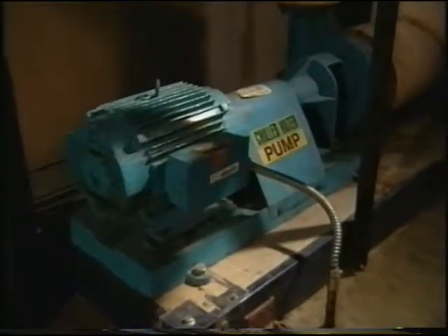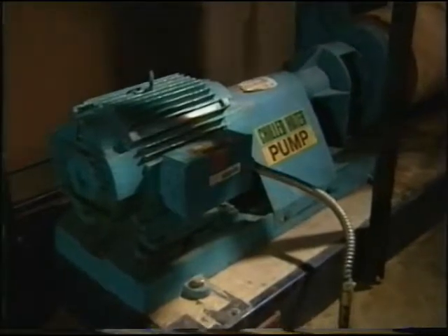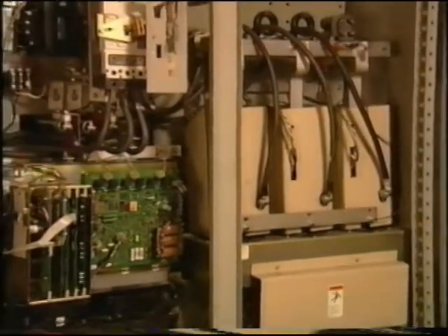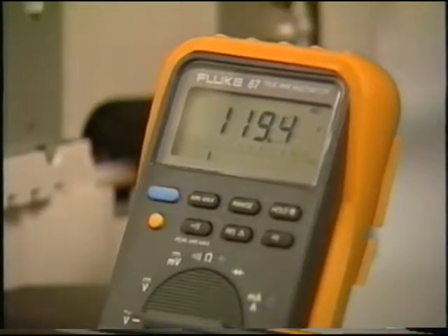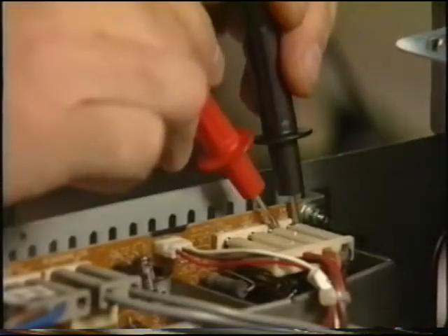Permanently installed loads are also Cat 3. Cat 3 includes big loads that can generate their own transients. Cat 2 covers the receptacle circuit level and plug-in loads. And Cat 1 refers to protected electronic circuits.